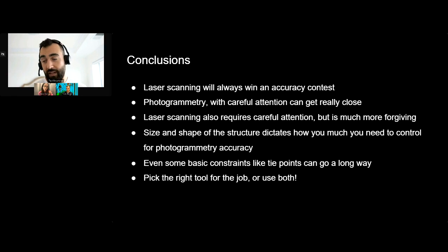So one thing I'm really excited for with X10 is the addition of RTK. That will get that positioning of the drone, that prior position, to be much more accurate, right, in that centimeter to centimeter range. And anything you can do to have more accuracy going into the process will result in more accuracy at the end of the day. So that scaling issue should be really improved with the addition of RTK or the differential GPS in a camera